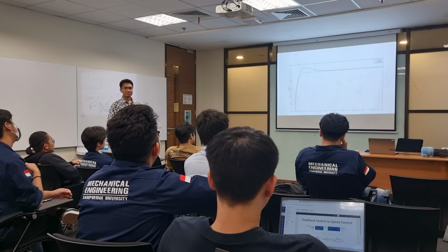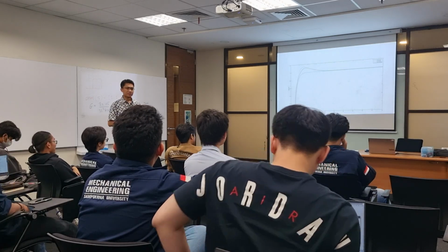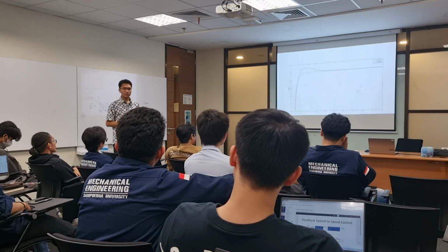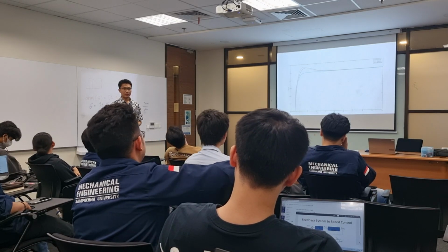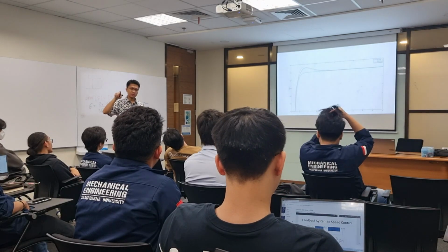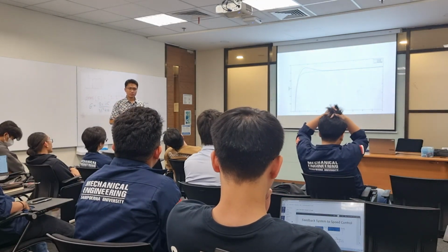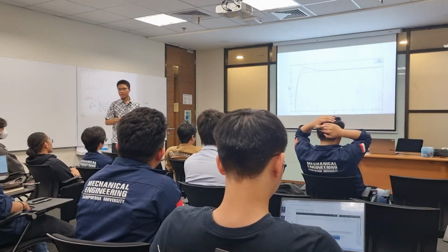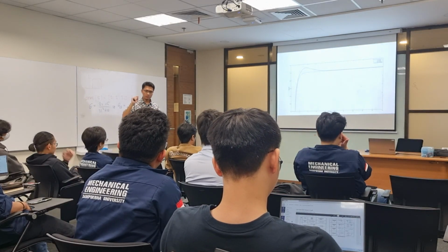So is it always the case that PI and PID is always good? When you have a step input, that's true. But when you have a ramp desired input, that's not true anymore. Okay. So it really depends on what kind of signal you want to follow.